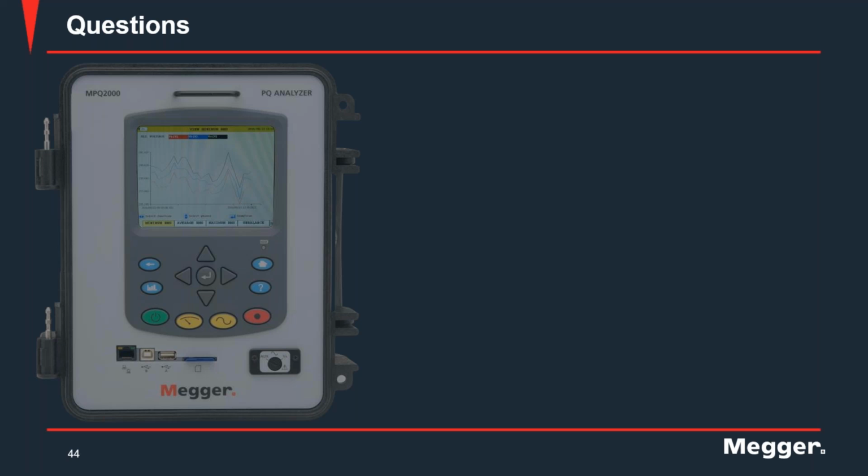Then there are some other standards like 61000-4-7, which talks about how to measure harmonics and interharmonics. There is 61000-4-15 that talks about how to measure flicker events. And one other I would mention is 61000-4-27, which talks about how to measure the imbalance in any given circuit. So there are a number of IEEE and IEC standards out there, and I just mentioned maybe 6 or 7 of those. But I highly recommend anyone who wants to do a PQ study should look at these IEEE and IEC standards.